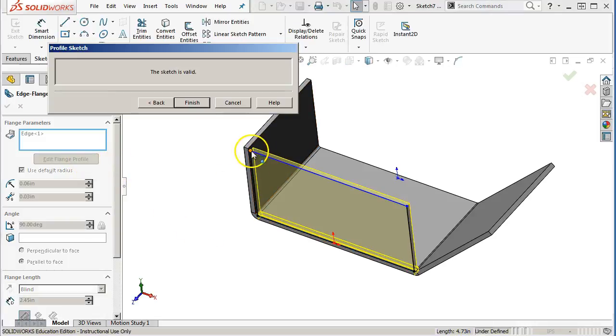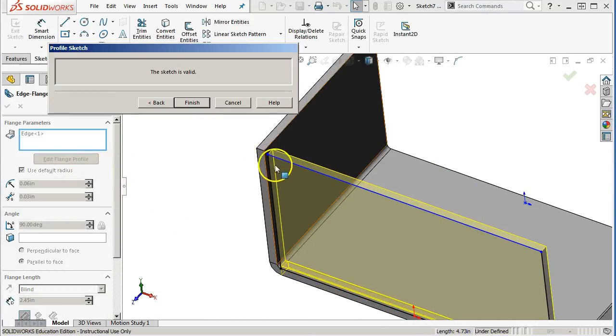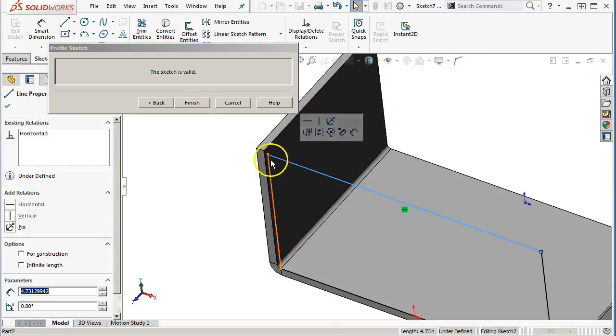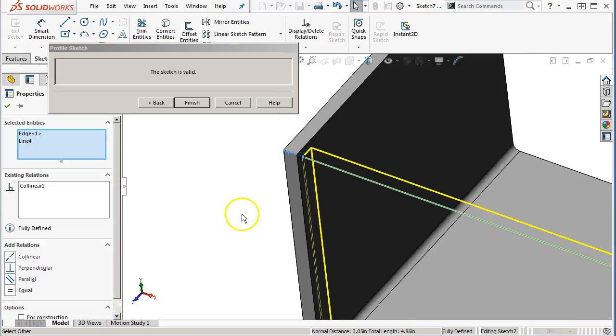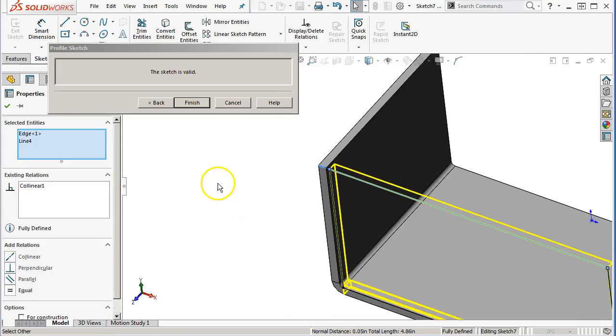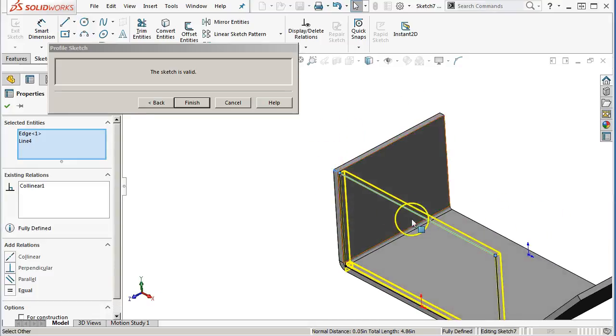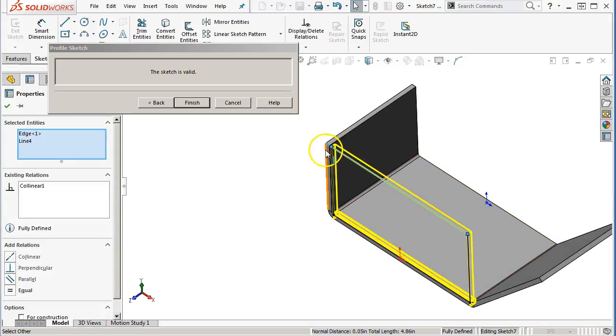Now when I edit this flange, in this case, let's go collinear to an edge. All right, so it brings it up, and now it says those will stay the same height. So I'm trying to build in enough intelligence, or enough logic anyway. I can't say intelligent, but enough logic that this will follow if I grow or shrink that flange.